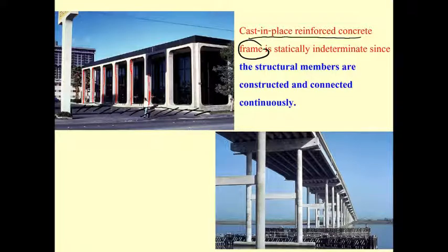You may do it simultaneously, or you may do it separately, whatsoever is up to the procedure you use in your construction. You're going to study that in construction management. Okay, you're going to talk about how to construct the structure in construction management. You may plan how to build it, and then you build all of your columns. Okay, after you finish the columns, you will cast the beam to link the columns together.